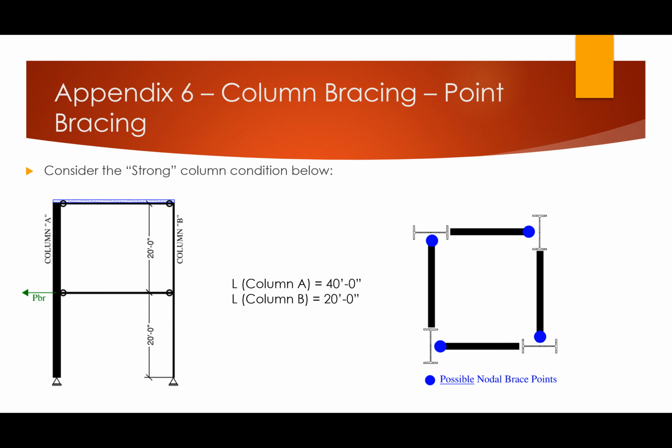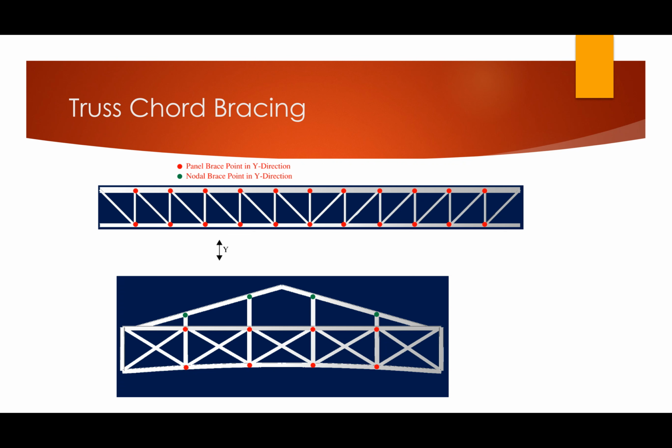But I hope it's clear now that simply putting those beams in there are not going to count as brace points. So in reality, a lot of these stress ratios should not have gone down, yet it did in our software. And this is really kind of the scary big idea I wanted to bring up.